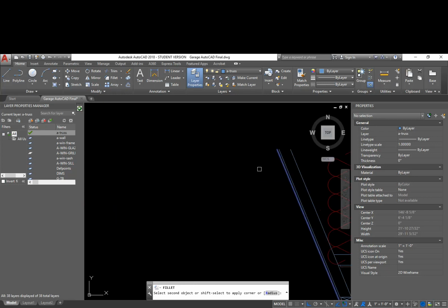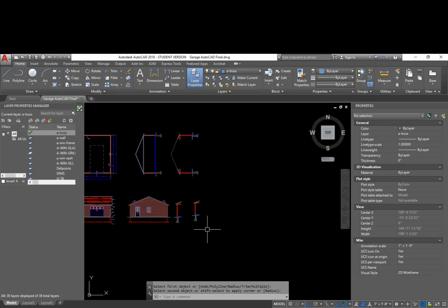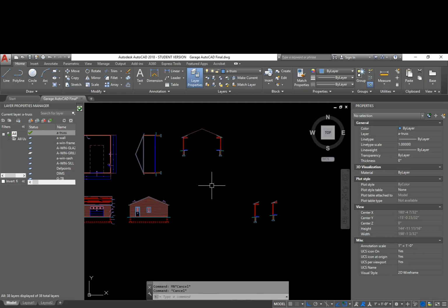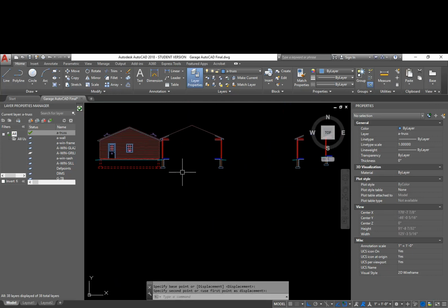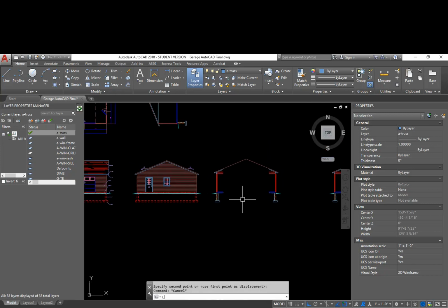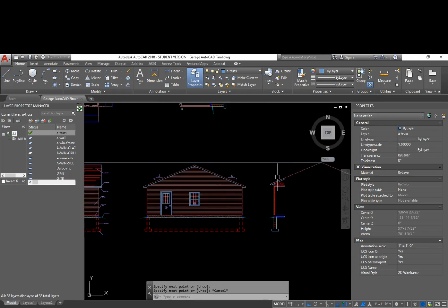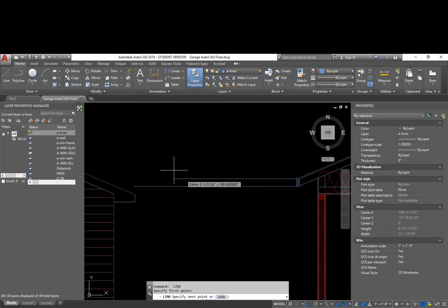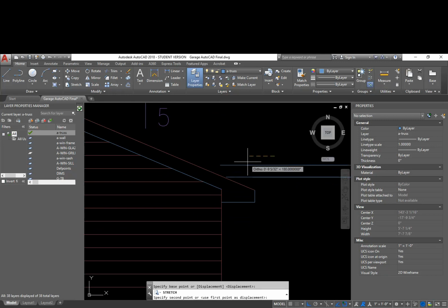And just to show you how this all works out, move these out of the way. These aren't going to be in our viewport anymore, by the way. Bring this back down here, line up the bottom of the footing with the bottom of the footing, move previous. Now whenever we look at this and we project our line over, now all of a sudden this roof is up higher. Not only that, our fascia is up higher. So none of this works out.